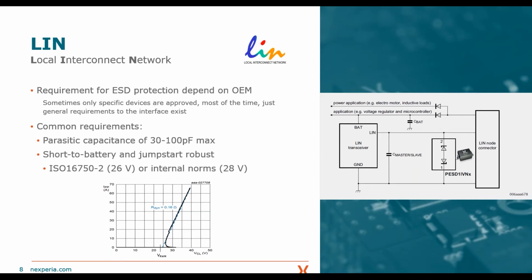On the right side, you see the basic schematic of LIN. This is the LIN transceiver itself, and we have the connector on the right side. What we learned from the last time, and we will see it during the whole presentation today, is our strong recommendation that you should put your ESD protection device as close to the connector as possible to protect your network, your LIN transceiver, the best.